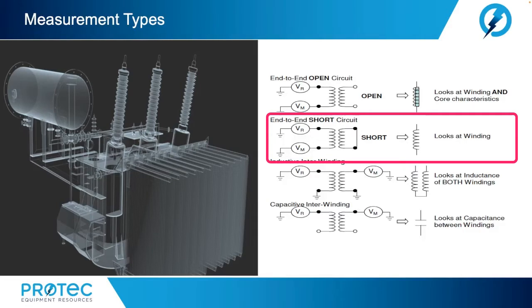The short circuit. A short circuit measurement is made with the same SFRA test lead connections as an open circuit measurement, but with the difference that another winding is short-circuited. To ensure repeatability, it is recommended that the 3 voltage terminals on the shorted windings are all shorted together.